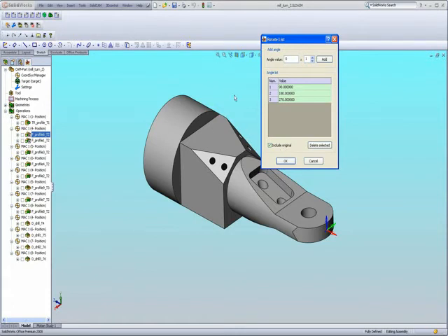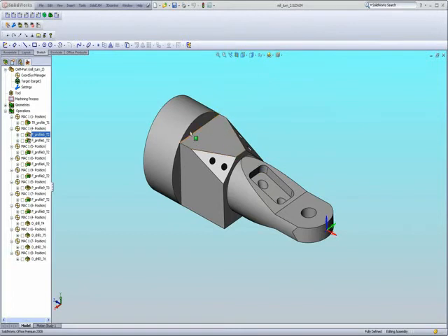Do the original geometry that I've chosen. Then turn the part to 90 degrees. Do that same geometry on 90 degrees, 180, and 270. That way I cover all the sides in this simple operation by simply creating one geometry and then just adding on the translation option of fourth axis.